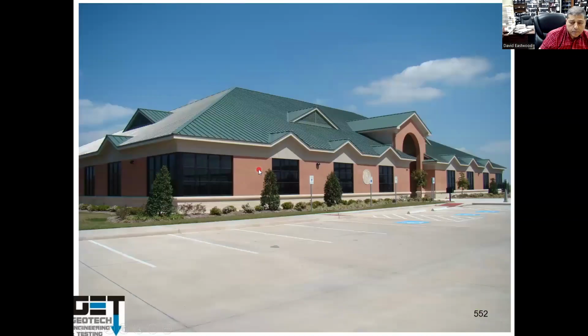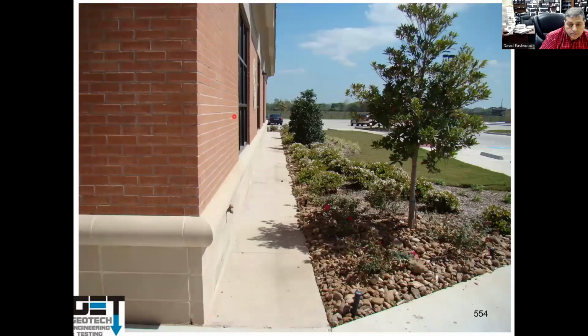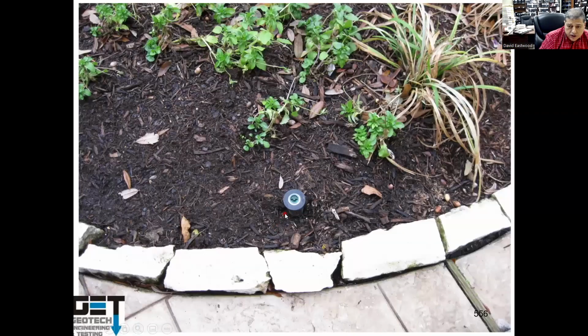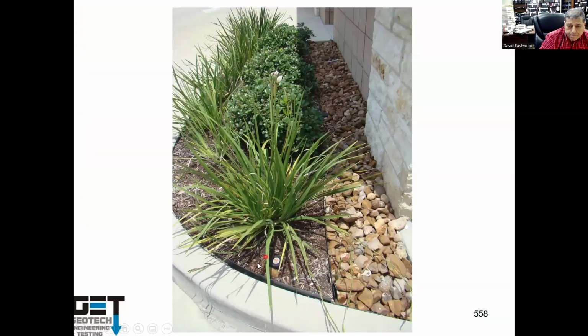It's bad design. This is a Fort Bend County building. These buildings have little skirts on them. Sprinkler system. Try to keep the moisture uniform underneath the slab. It's only 2 foot. It's not very much, but it helps. See the sprinkler systems? If you put sprinkler systems, make sure it's uniform all around, not only on just one side. You got concrete here, you got sprinkler system. This part of the building has bed liner, gravel, sprinkler system. This part of the building can move.